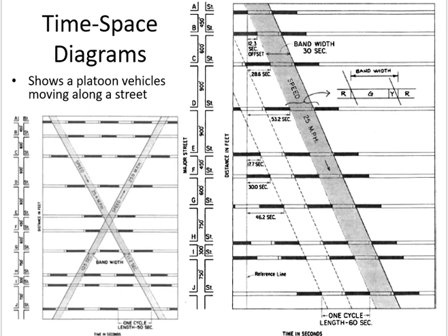So whoever is coming in these 30 seconds, for this example, the bandwidth is how much? 30 seconds. So whoever comes in these 30 seconds will continue moving at the speed. If somebody comes before this, he has to stop, right? And somebody comes after this, again he has to stop. So he will be away from the progression. Progression is in these 30 seconds. Okay? Clear?